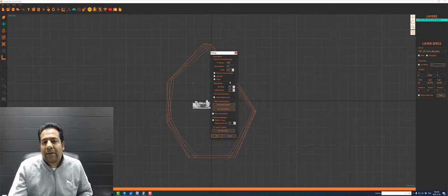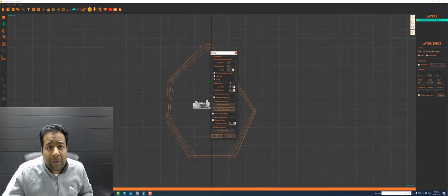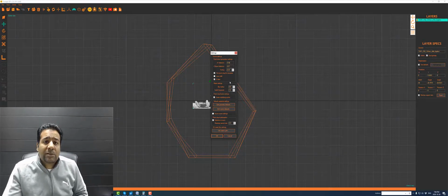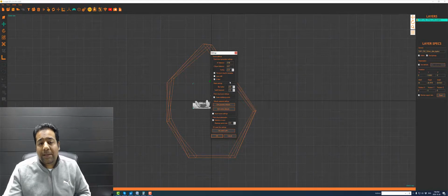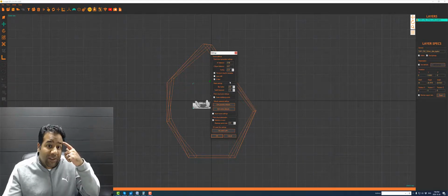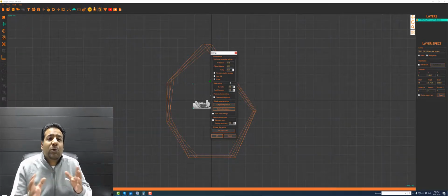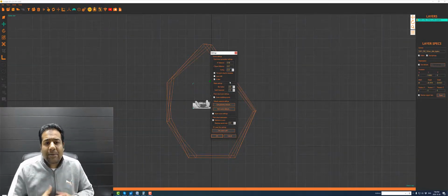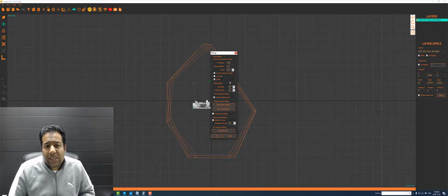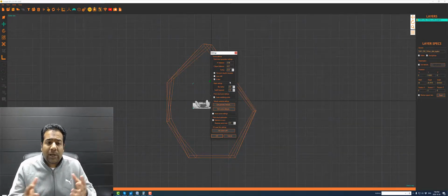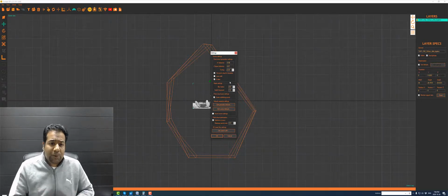So if you go to 0.05, yes, it'll increase resolution. It'll also increase the probability of cracking. So you might come across certain crystals with a lot of white that will crack, and you're going to have to keep that in mind. So that's another variable to think about, which you really don't want to. You want to try and have settings where you don't really have to worry about how much white is in the image. The other thing is as you decrease this, it increases the number of points, and as it increases the number of points, it also increases the burn time too.